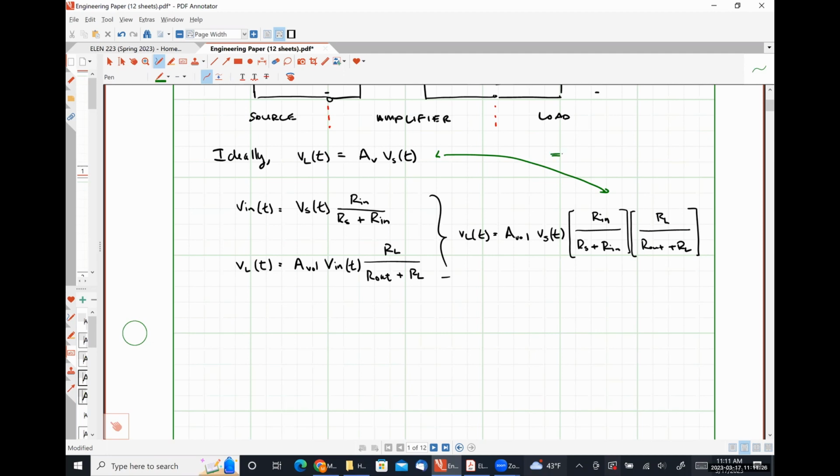So for the ideal case, Rn is effectively an open circuit. We can see that in our practical op amps we've been dealing with input resistances on the order of mega ohms or larger. That's generally what these have been designed to do. But if we look at this right-hand expression, RL over R out plus RL, how do we make this look like 1?